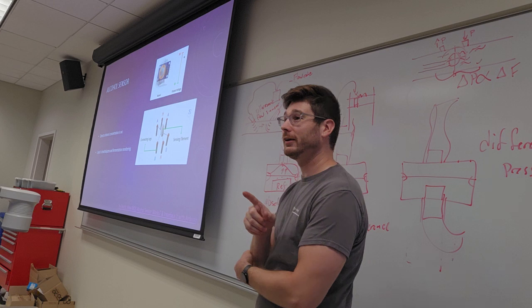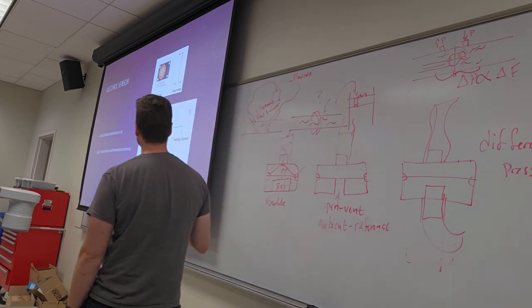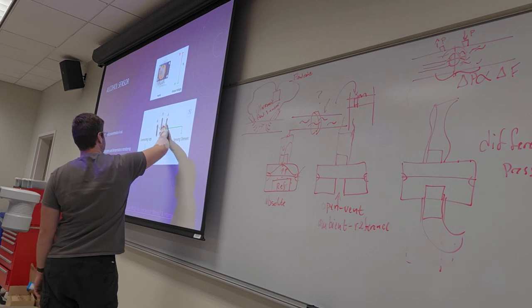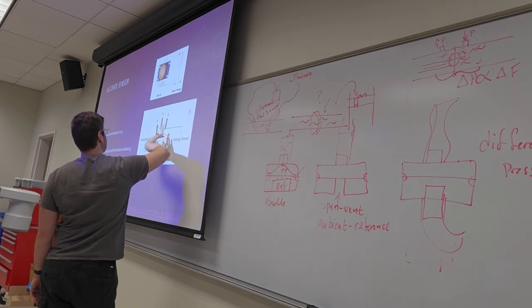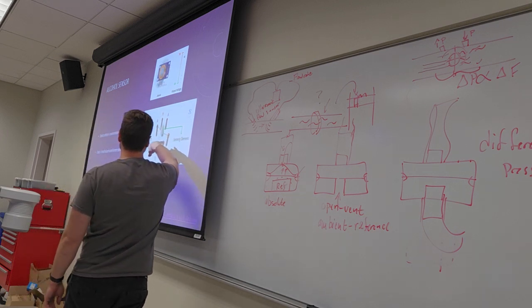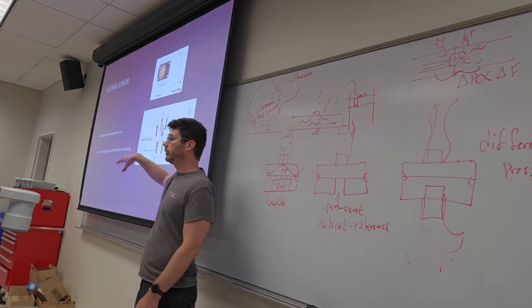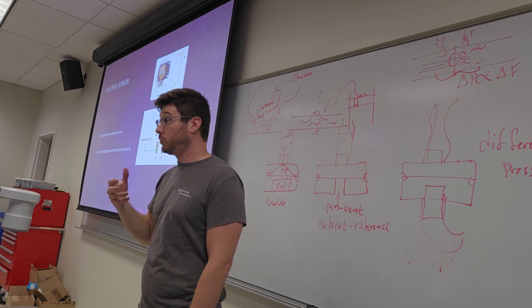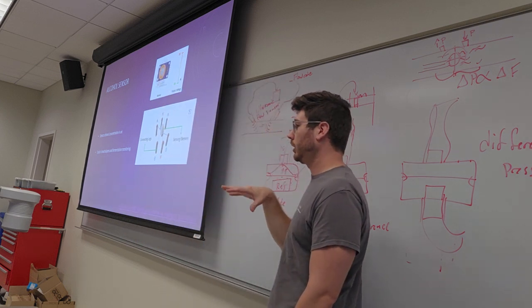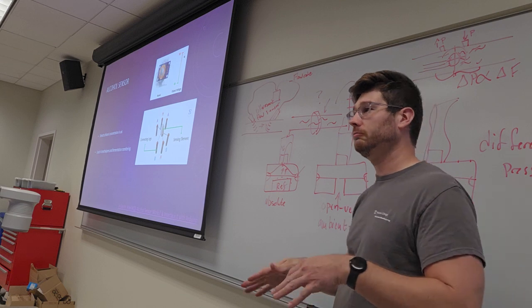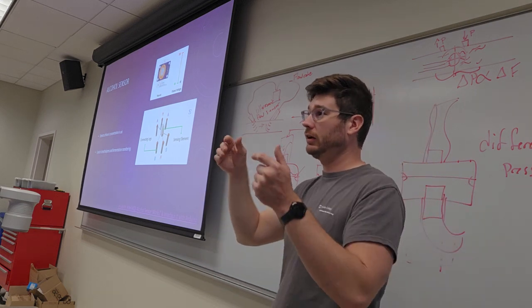Okay, so they have a very, very small heating element inside of them. This is actually a ceramic heating element, and each of these legs either connects to the sensing element or a very small heater, right, a little coil that's inside here. So it brings it up to pretty high above ambient temperature. I think it's around like 100 degrees. Takes a reading and then powers down the sensor again. That's a cool, next time it comes up, it takes the sensor reading and then goes back down.